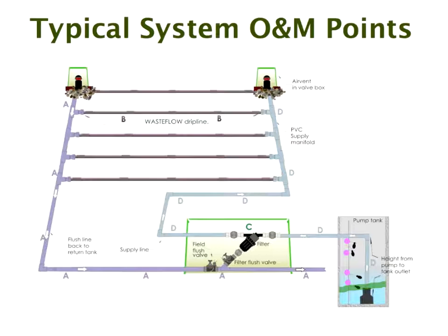From there we go through the filter system. The filter system can vary, as we discussed, with different types of filters. But the filters, again, I believe every 6 months should be taken apart, cleaned, and put back together again. With some filters, like a low-cost screen filter, the contractor will keep clean screens in the back of his truck and just take out the dirty screen and put in a clean screen and take the dirty one back to the shop to clean. In the case of discs, he might have to take them apart and clean them and put them back in, but they should be checked, because things do go wrong.